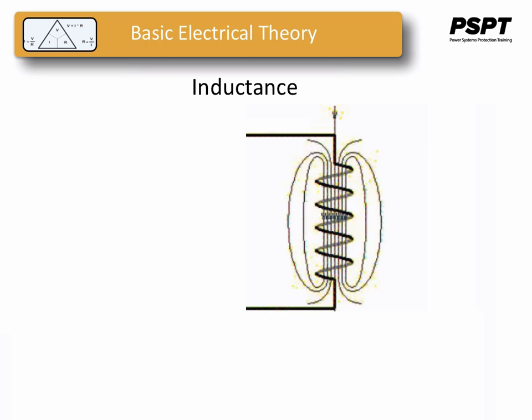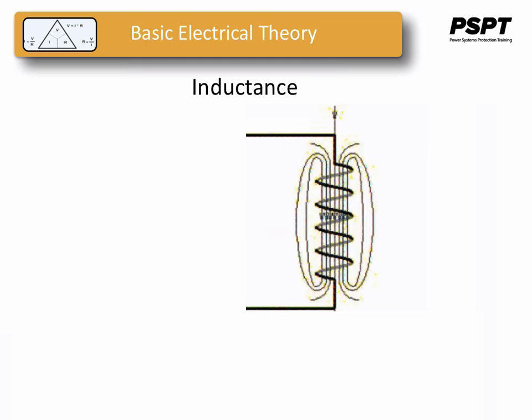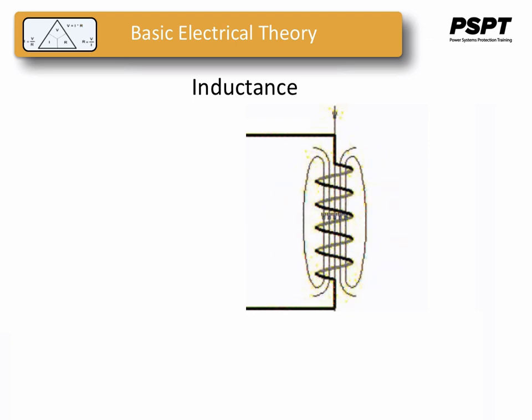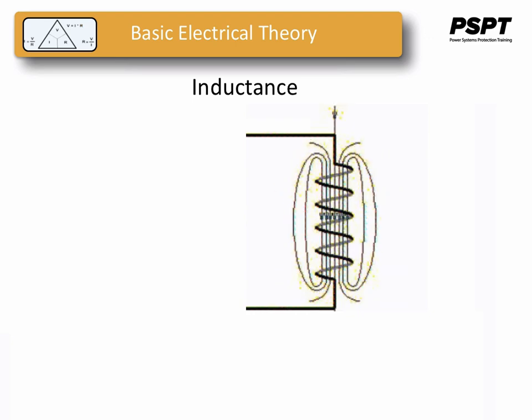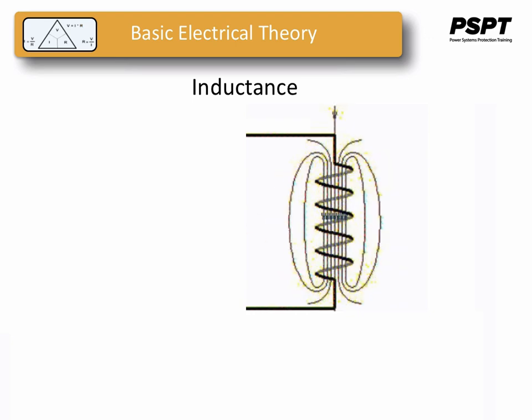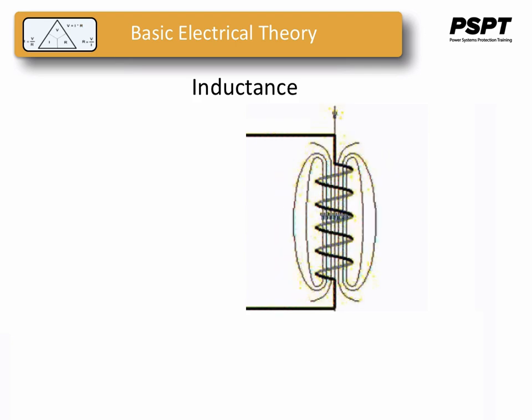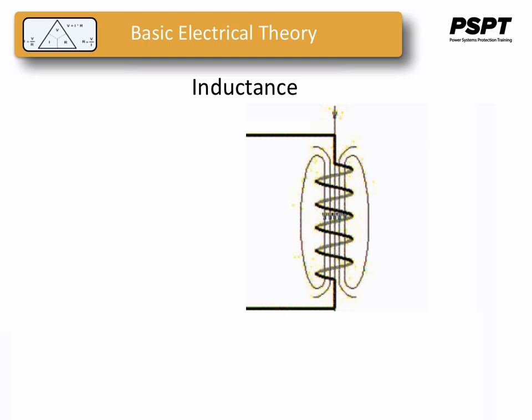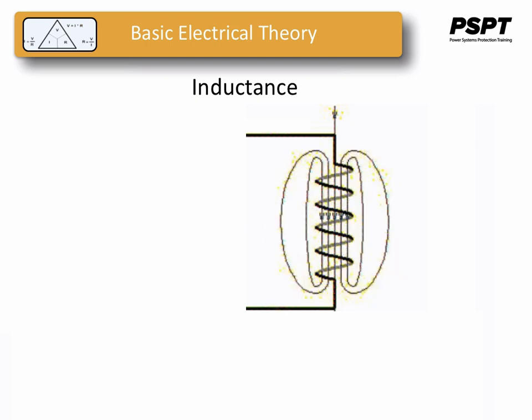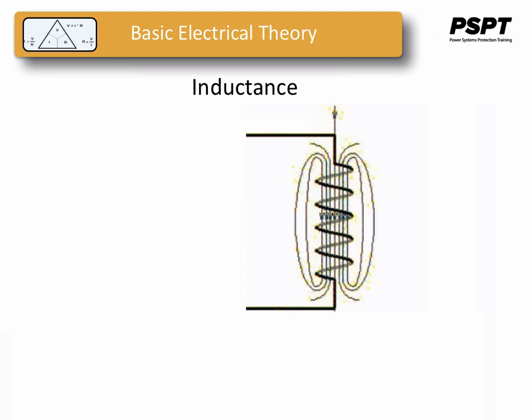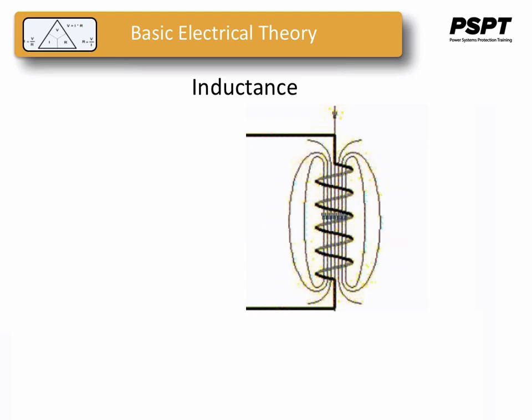As the electric current produces a concentrated magnetic field around the coil, this field flux equates to a storage of energy representing the kinetic motion of electrons through the coil. The more current in the coil, the stronger the magnetic field will be, and the more energy the inductor will store. Because inductors store the kinetic energy of moving electrons in the form of a magnetic field, they behave quite differently than resistors, which simply dissipate energy in the form of heat.